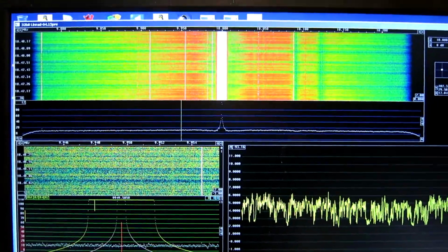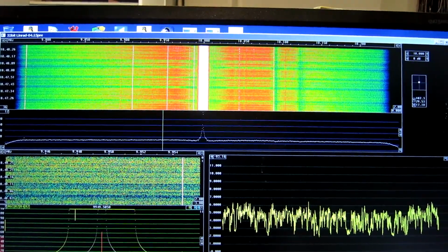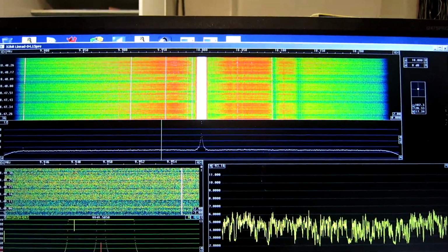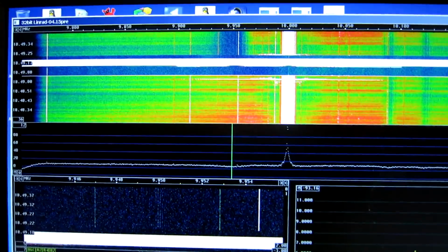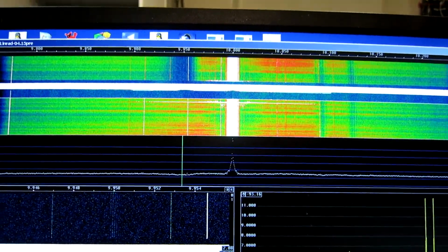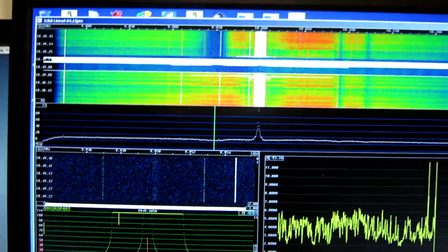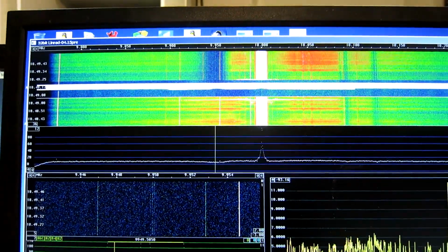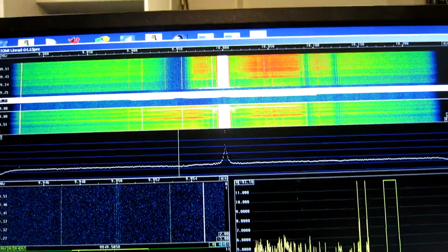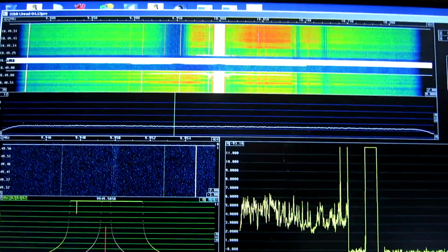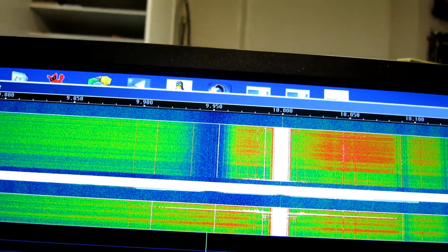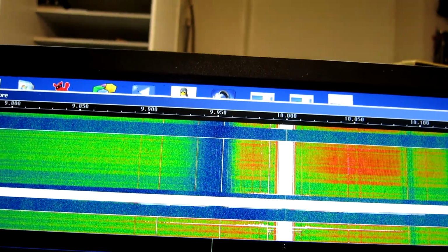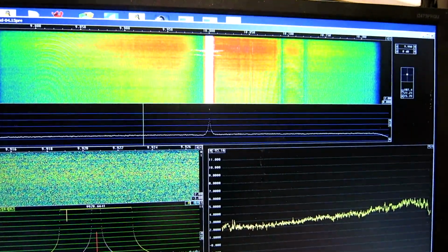Now I have a situation with an unstable signal. So I connect the notch filter for a 50 kilohertz notch between the signal source and the measurement system. And it's immediately clear the problem is in the oscillator. And I can switch the oscillator off by disconnecting the feedback loop, for example. And there is a very small difference in the notch. Here is the stability problem.